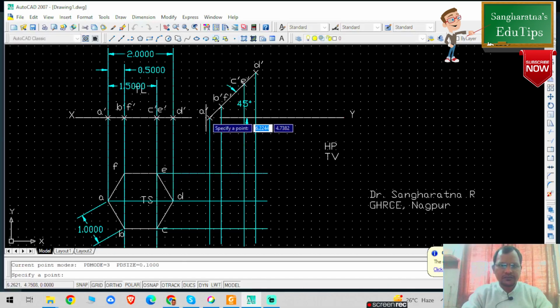Now I am going to mark the points at the intersections. This is the A projection line and this is my A, so this will be my point A1. Similarly, this is my B projection line vertically and this is my horizontal projection line, so this is my B and this is my F. Similarly, from C there is a vertical projector and from C and E there is a horizontal projector, so this will be my point C and this will be my point E. And from D there is a vertical projector and from D this is the horizontal projection on this point. Now I have marked all the points.